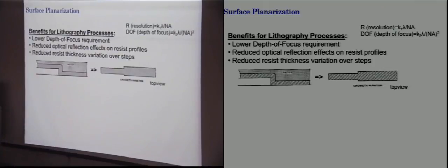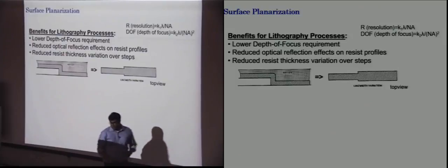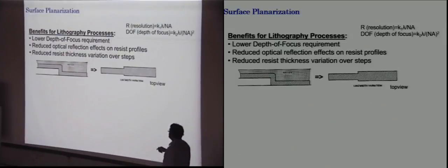Okay. So in addition to the wavy nature that we talked about in the tutorial, these kind of effects can also happen. And of course the thickness of the photoresist is much higher here, much lower here. This also will bring about variations in the structure, variations in the lithography process. So this is one problem we are having, poor planarity.